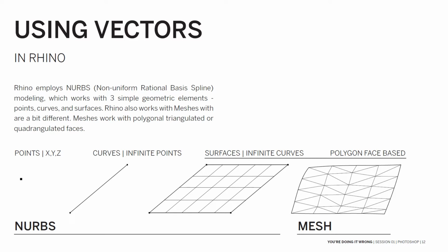But every surface and object has a U and V direction, which is basically the local X and Y direction of that surface. So a surface's coordinate system can exist separately from the world coordinate system in terms of orientation and mapping of the surface.